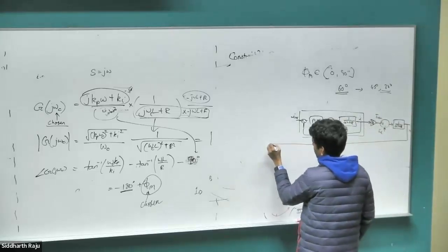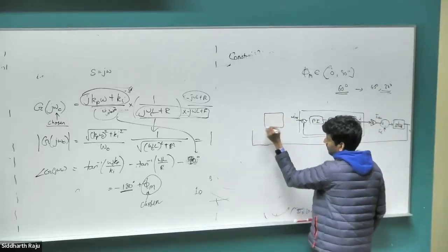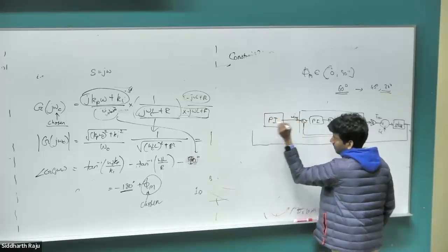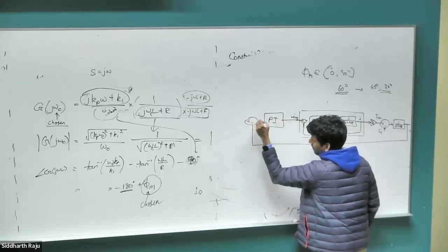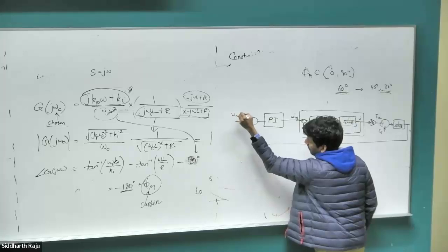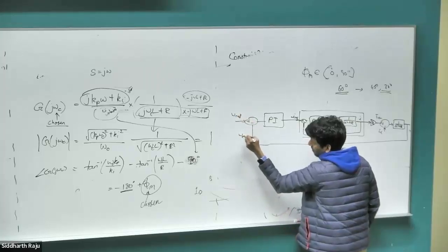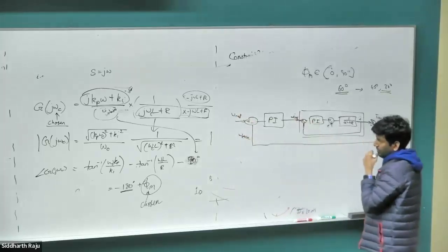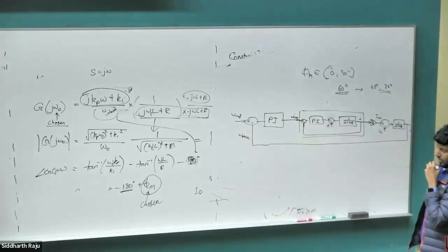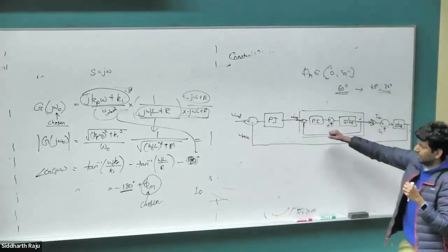And what I'm going to now do is put another PI controller. Omega reference, omega FPK. And the output of this PI controller is going to be the current reference that I'm going to be feeding into our previously designed current controller.